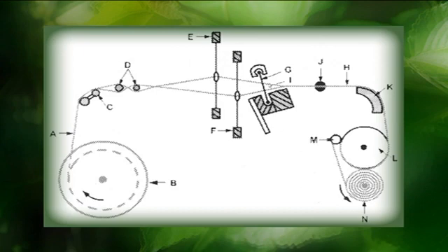At this point, cloth is formed and is held firmly by temples J to assist in the formation of a uniform cloth. The cloth H then passes over a front rest K, around an emery roller or take-up roller L and a guide roller M, and is finally wound onto a cloth roller N.